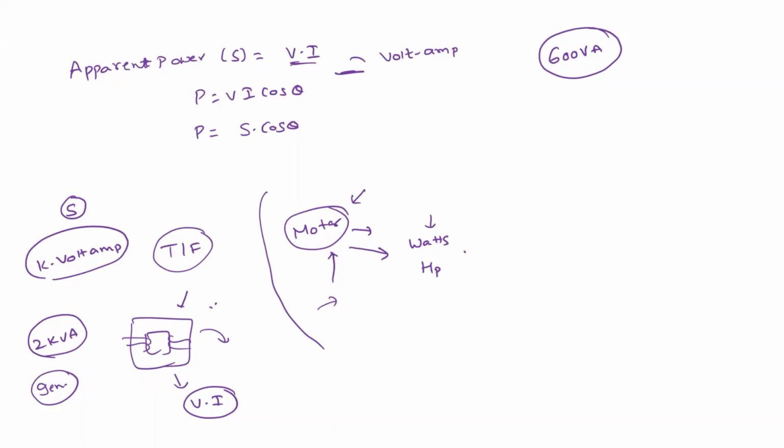So we have two powers: P equal to VI cos theta, and Q equal to VI sin theta. Agree? Sir, it means we don't know what kind of circuit we are using, that's why we write volt amperes? Yes, what kind of load you are connecting, for example a UPS. You can connect any kind of load: a computer, or your home appliances, anything. The actual power consumption depends on the load, but they don't know what load is connected, so that's why they are rated in volt amperes.